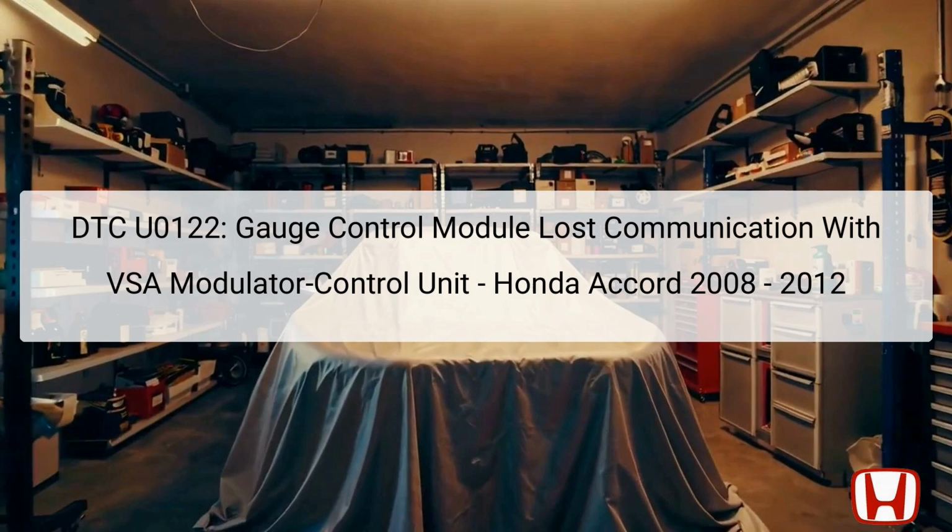In cases where the HDS fails to communicate with the VSA unit and no additional Diagnostic Trouble Codes, DTCs, are registered, other underlying electrical issues should be investigated to ensure a thorough diagnosis.